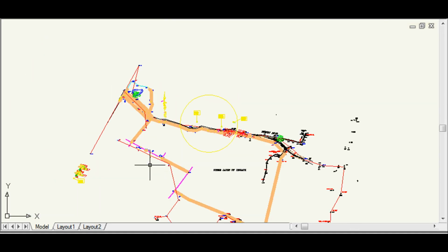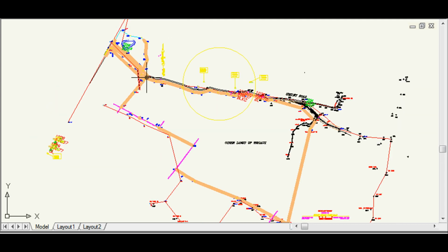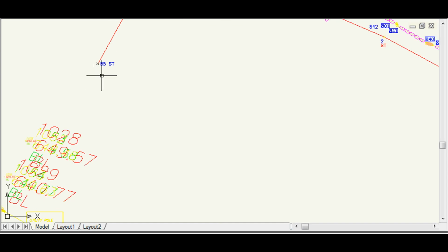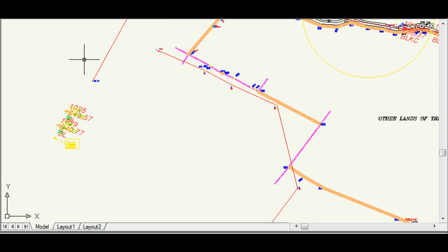And so what we would do for aerial survey is we run this same baseline for control, and then we set up out where we can get visual contact from the air, and we'll put two big strips of white plastic or white fabric down and make an X over the pin. That way, when they fly over for the aerial, they can find the pin that we shot control for and line it up in the photography with the exact precise control data. And then from that, they're able to calculate elevation and topographic data from the photography and the control data. I hope that makes sense to you, but basically what we're doing is building a topographic map from aerial photography and solid precision data.